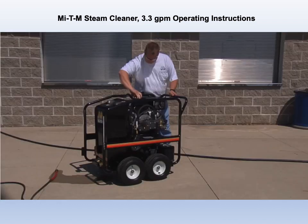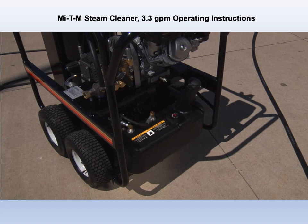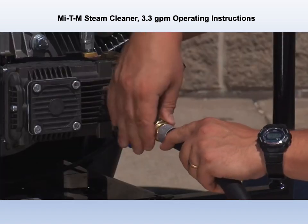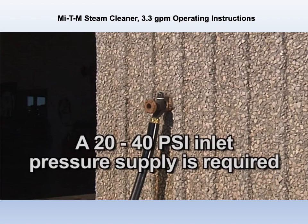Use 85 octane gas for the engine and either number 1 or number 2 diesel fuel or kerosene for the burner supply tank. Connect a garden hose to the pressure washer and the other end to your water supply. A 20 to 40 psi inlet pressure supply is required.